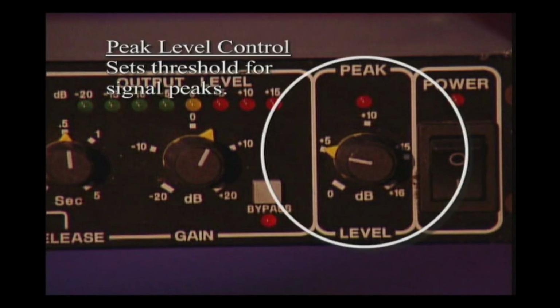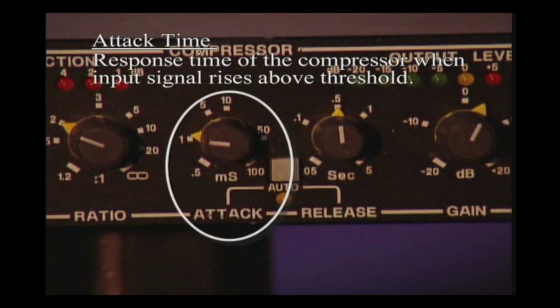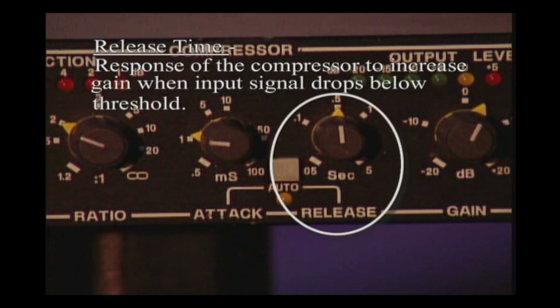The peak level control allows you to set a threshold for signal peaks. It basically helps prevent clipping by setting a certain threshold. The amount of time the compressor takes to respond when the input level rises above the threshold is called the attack time and is usually fairly short, under 100 milliseconds. When the input level is above the threshold and then drops below it, the compressor will take some time to increase the gain. This is the release time of the compressor, which is generally longer than the attack time, possibly up to a second or 2.